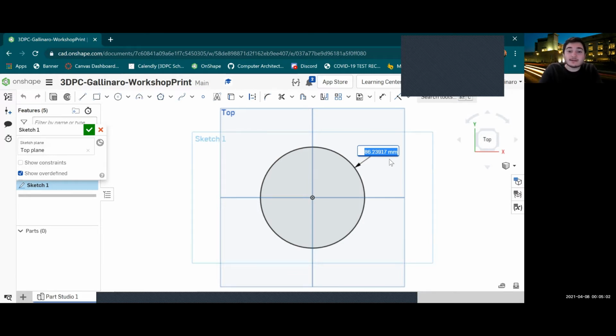So we're going to be using decimal numbers with, I guess, more numbers towards the end. So yeah, not everything's going to be one number. So it's going to be 13.97. So I'll just give it a second and then click enter. And you also don't have to type in millimeters, since you already set the document setting to millimeters, you could automatically just type in the number and it will